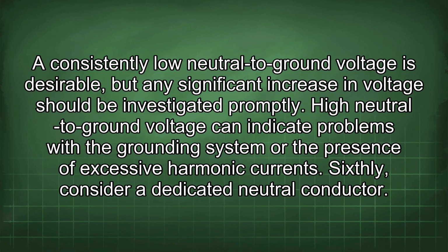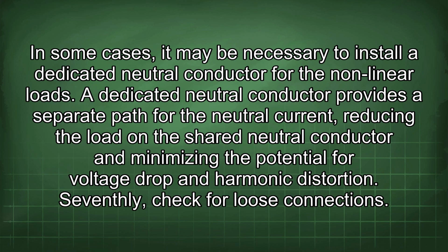Sixthly, consider a dedicated neutral conductor. In some cases, it may be necessary to install a dedicated neutral conductor for the nonlinear loads. A dedicated neutral conductor provides a separate path for the neutral current, reducing the load on the shared neutral conductor and minimizing the potential for voltage drop and harmonic distortion.